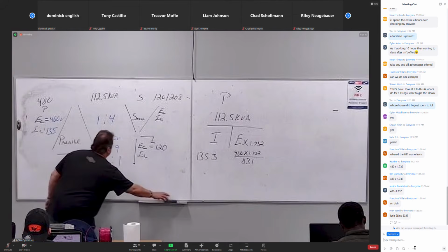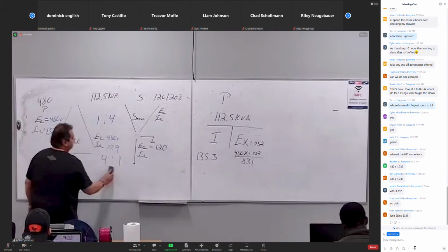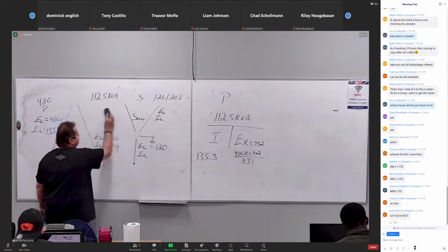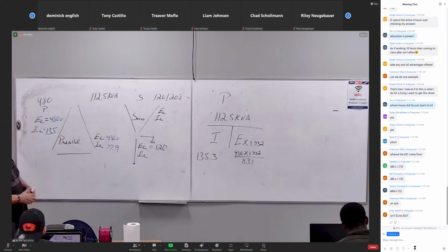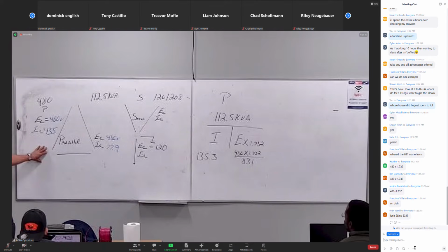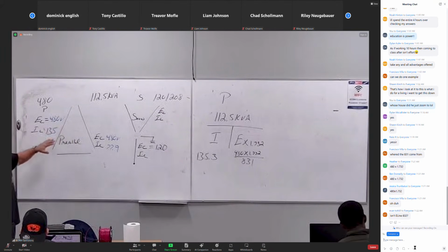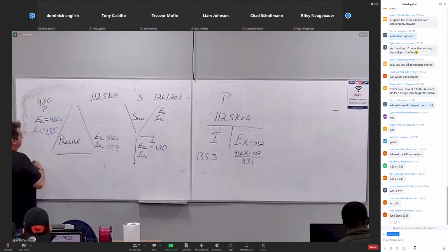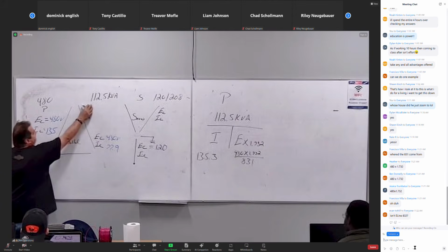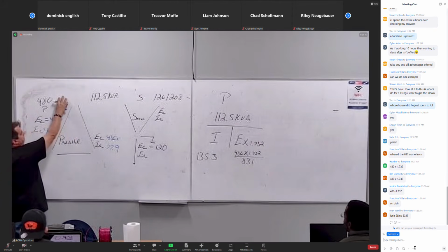Okay, I want to show you something. I'm not looking at the Y at all, and I'm not looking at the ratios at all. We're just solving the delta. Are you with me so far? We know that in a delta, voltage stays the same because it's a parallel circuit. We agree with that, correct? We have our kVA up here, that's the load.